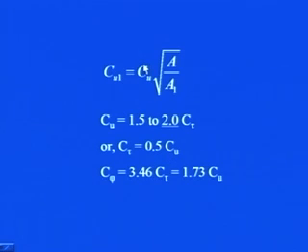So, knowing the value of Cu for the test plate, I can get this value of Cu for the foundation. Once this Cu value is known to us, we can substitute here in this particular expression and can get the value of C tau. Then again we know that C phi is equal to 3.46 C tau.